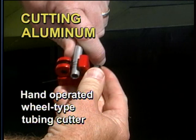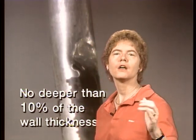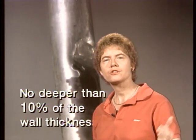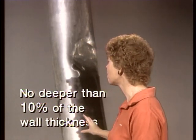cutter. Now let's assume that you've got scratches or nicks in an aluminum alloy tubing. Scratches or nicks can be repaired by burnishing the tubing unless it's particularly bad. And how bad is particularly bad? Well, if the scratch or nick is not in the heel of a bend, then you can repair it by burnishing, or if it's in a straight section, it can be no deeper than 10% of the wall thickness.